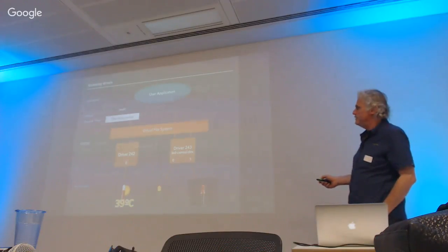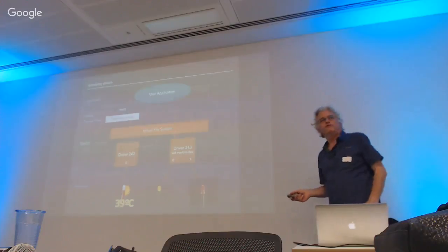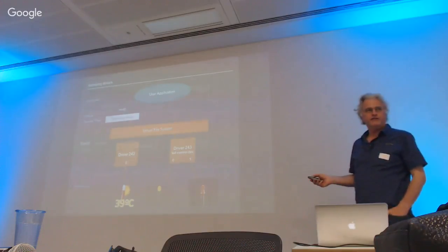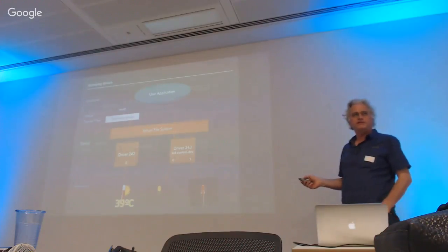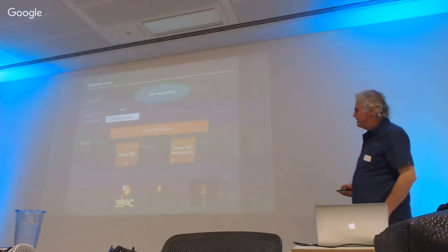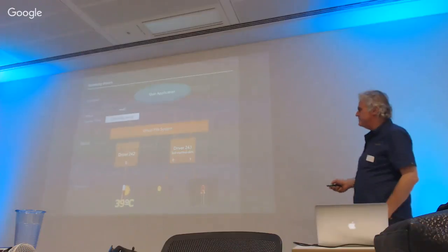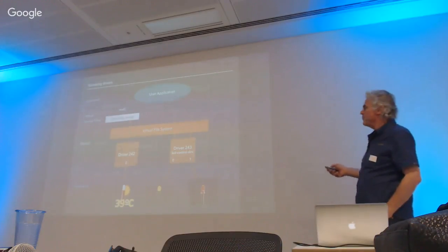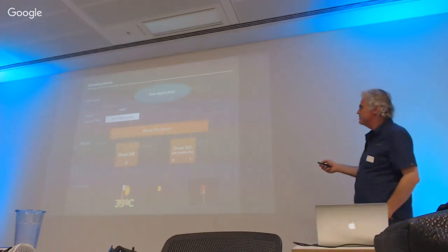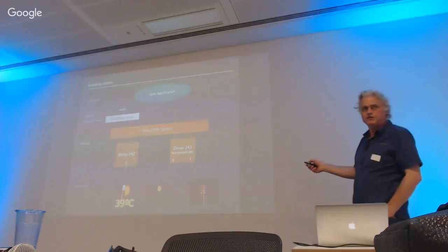For example, we could call it temp sensor. And we create it in a directory called /dev. If you look on your Raspberry Pi, you'll see a /dev directory which contains these device files. Let's say we now want to write to these LEDs. Maybe the temperature's too high, and we want to switch the red LED on. So I'll use the application. This can be an application that's written in Python, anything, it doesn't really matter, C, Java.